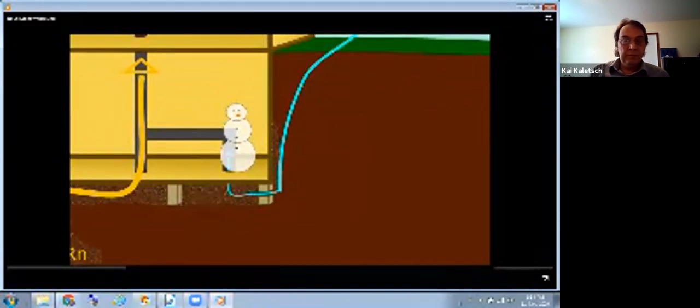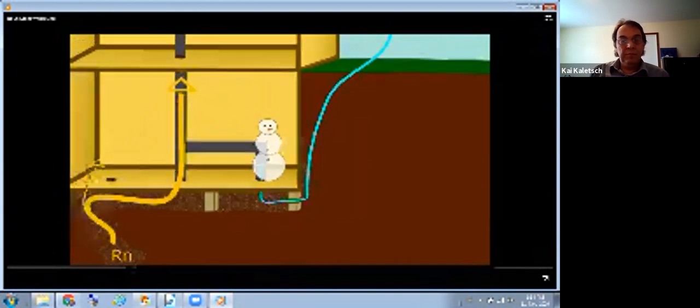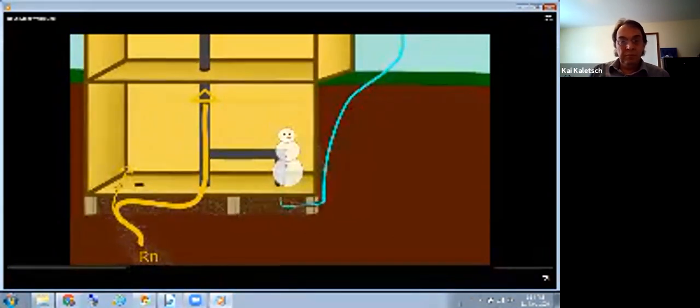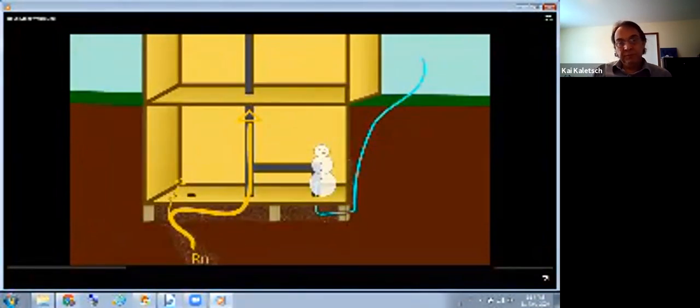It also lowers the suction on the other side by pulling in outdoor air. Plus now you have a large unsightly jumper. Even worse, the problem might not have even gotten solved. In theory, the mitigator depressurized the entire slab and reversed the airflow through the cracks, but this isn't necessarily the case. The actual pressure at the crack was never measured. There might not even be access to the crack if it is at the expansion joint under a finished wall.